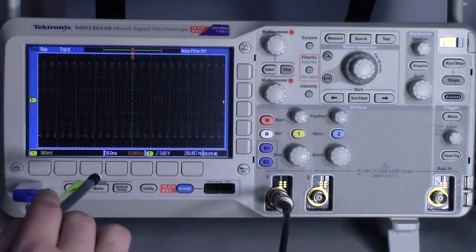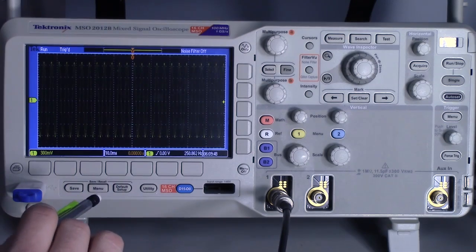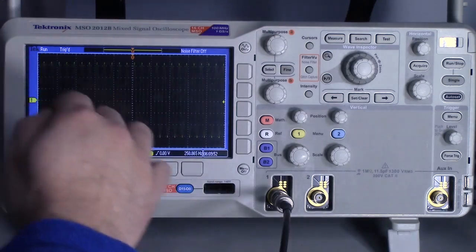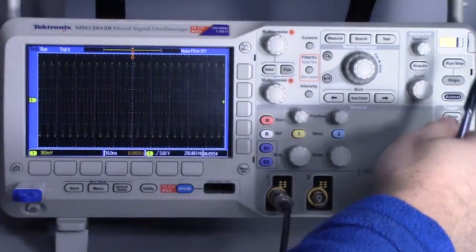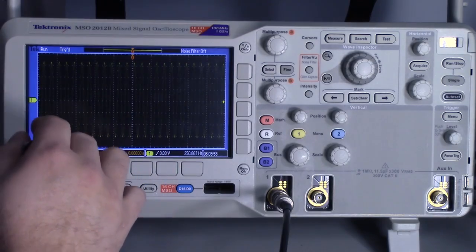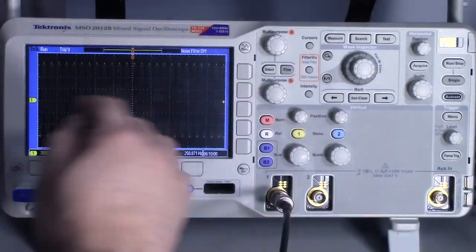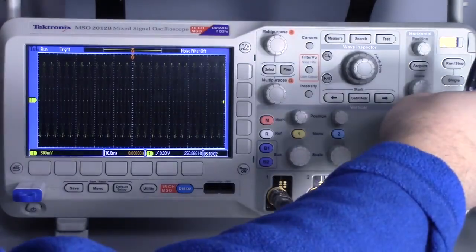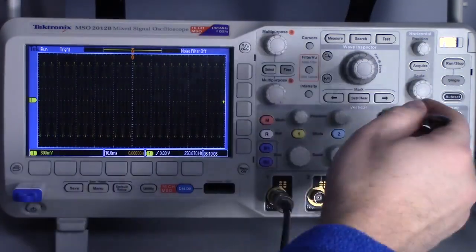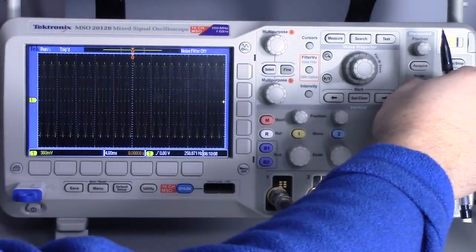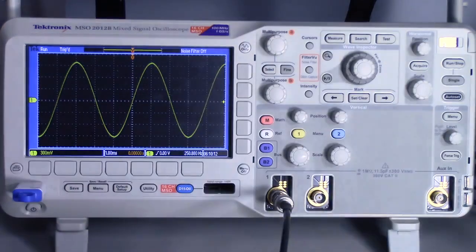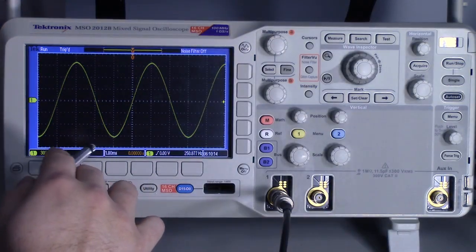So now I've changed the function generator frequency to 250 hertz, and now it's showing far more waves, far more periods. I want to actually be able to see just a couple of waveforms here. This is just way too much information on the screen. So I want to change the horizontal scale from 10 milliseconds to smaller. So I'm going to decrease this. And there we go. I'm now down to 1 millisecond per division.